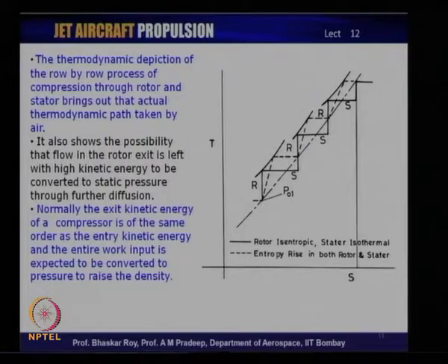If we look at the thermodynamic depiction of a row by row process of a compression through rotor and stator, we know the rotor does work and the stator does not do any work, really speaking. We will be talking about those things in great detail in the chapters to come. The thermodynamic path taken by the air through these compressors through rotor and stator can also be shown in terms